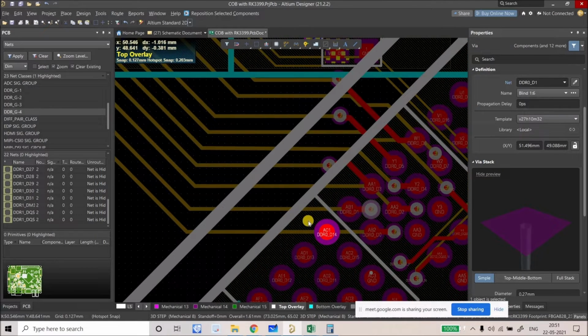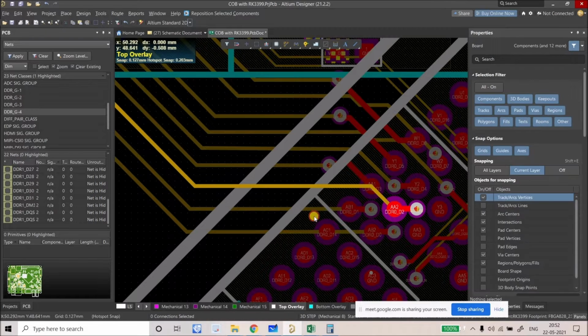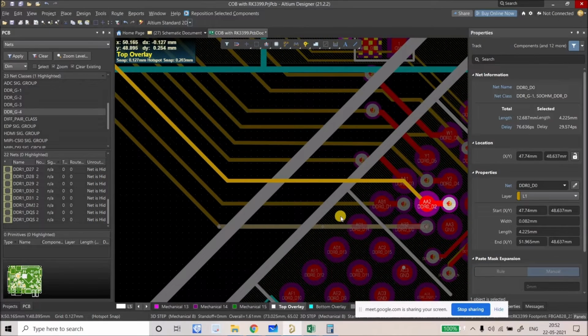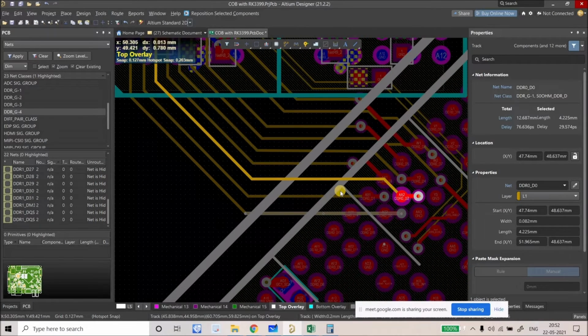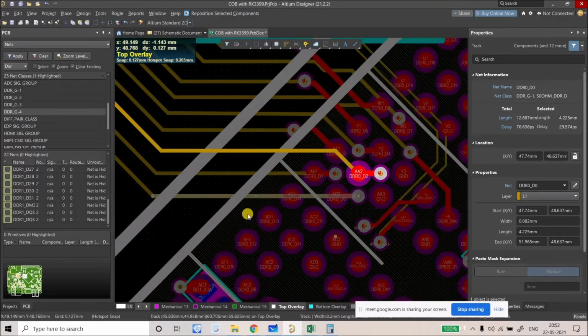The solution for this is that these 2 or 3 tracks, which are coming from another byte group section, should not be there. They should be outside of this section. Only then can you place the via and fan out this thing. You'll not find this in any book, and it is not a rule, but I found that for this particular SOC, from my observation, if you don't follow this, it is really difficult to route all these byte groups.